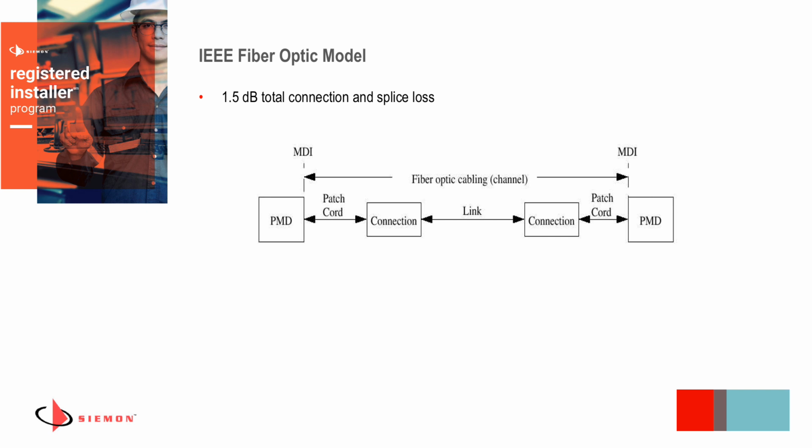Your splices themselves might typically only be about 0.1 dB with a fusion splice, and connectors are typically going to be 0.5 dB or better. So not an issue, but it's good background to get an idea that these two groups do work together and what their understanding of the overall loss should be from the connector side. In terms of the cable side, they're in agreement with the TIA limits for the cables, so that's factored in as well.